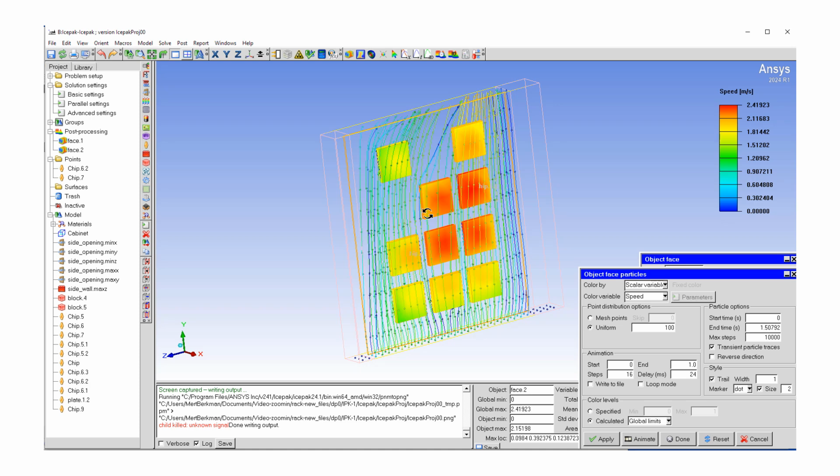But what we did was, first in the bigger model we solved for the whole domain, and then we cut a small section out of it as a submodel, where the flow information at the boundaries is coming from the main model, and then we have different geometry inside the submodel, which is finally resolved.